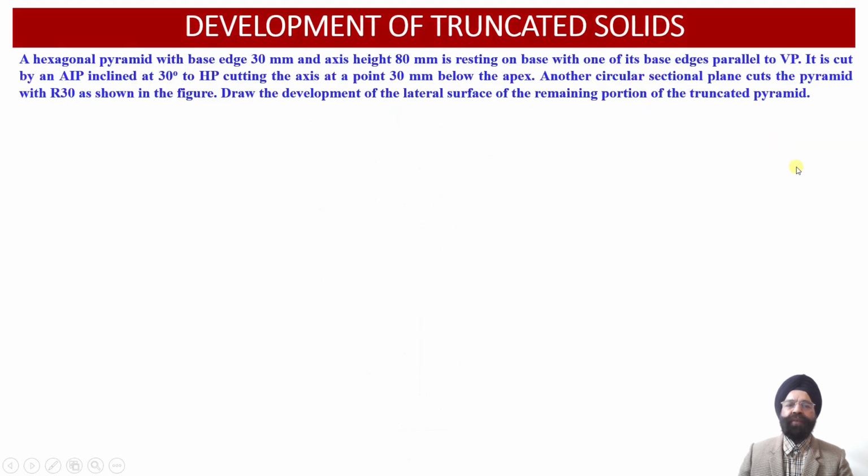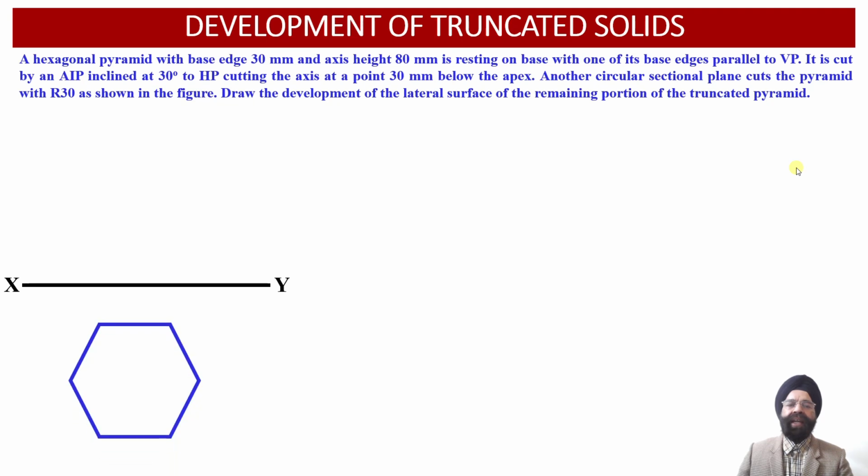So now let us proceed with the evaluation of the top view and the front view projections corresponding to this hexagonal pyramid. When the observer looks at this hexagonal pyramid from the top, we are going to obtain hexagonal projections onto the horizontal plane over here. And the edge length, we know, is equal to 30 mm. So the 6 points of the base A, B, C, D, E and F, we have appropriately marked onto the top view projections corresponding to this hexagonal construction.